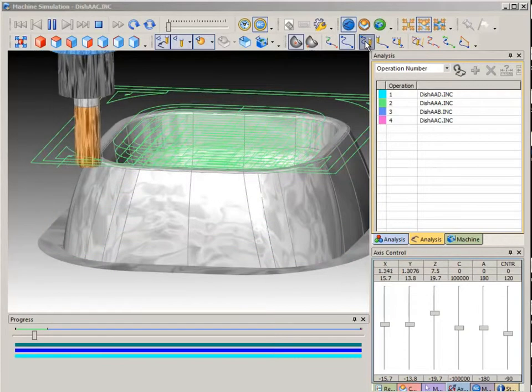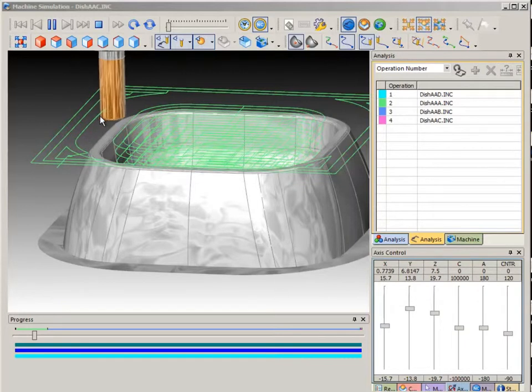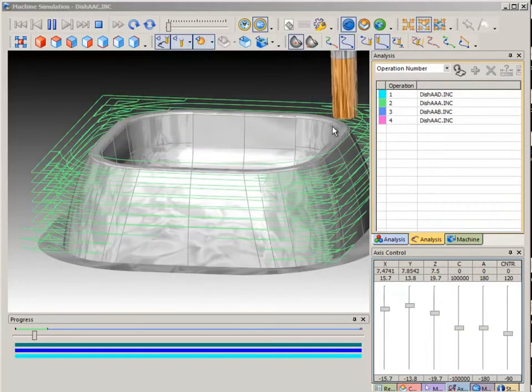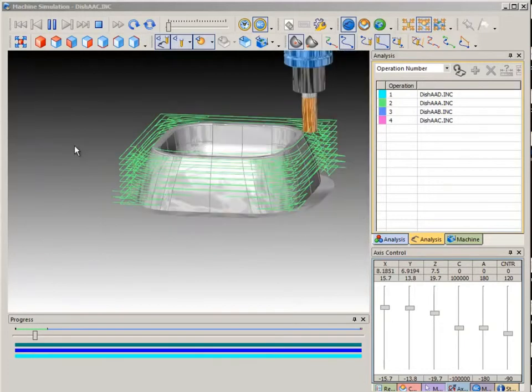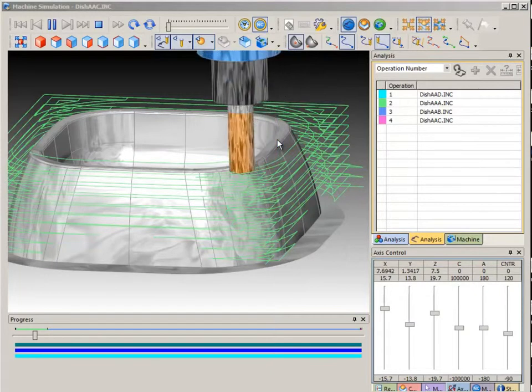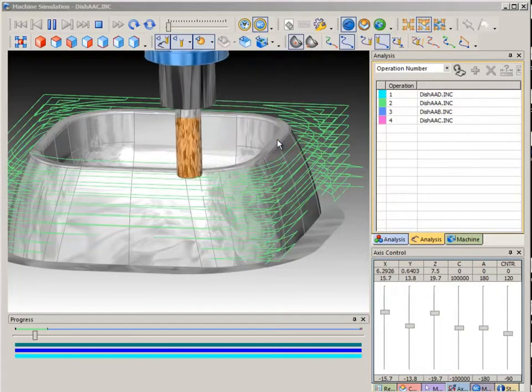By selecting Follow toolpath, as the toolpath is simulated on the screen, it will draw that toolpath actively on the screen as it simulates. Notice here in the back window. You have Trace, which is when the toolpath is displayed all actively on the screen, and then as the toolpath simulates, it removes those lines that it has played.